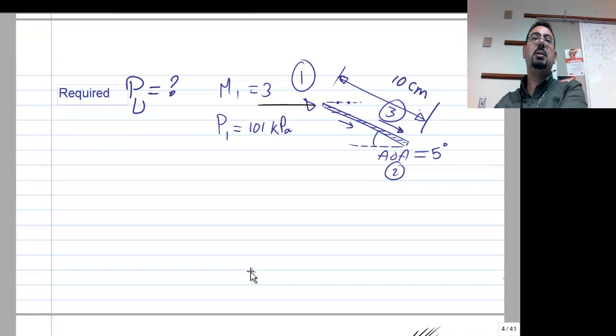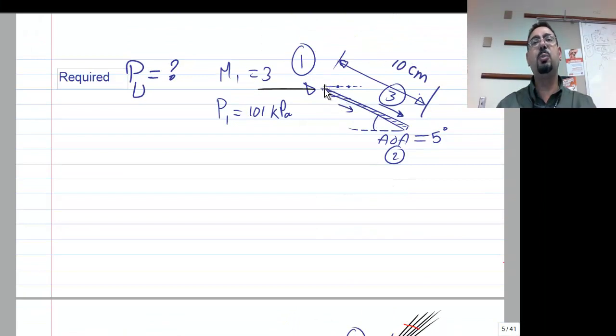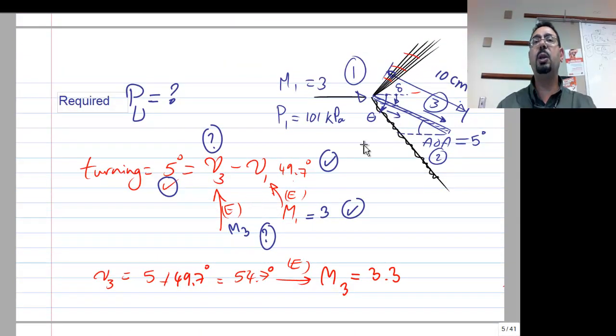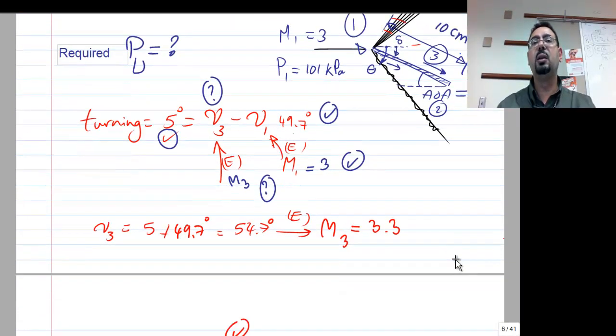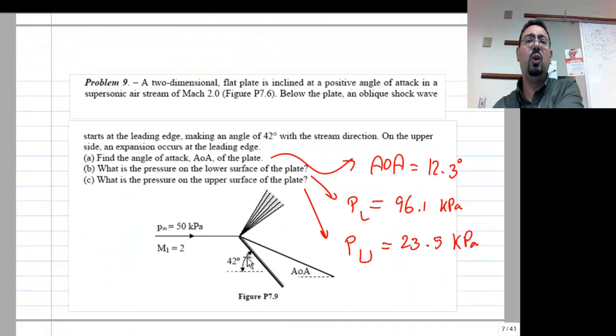So in this chapter, we would like to calculate the lift and the drag, in dimensionless form, which we call CD and CL, drag coefficient and lift coefficient. The first step is just to get the pressure, and that's what you did in homework 7. You go over every corner and say expansion fan, oblique shock wave, and solve the expansion fan with its equation, solve for the pressure, and then solve the lower shock wave.